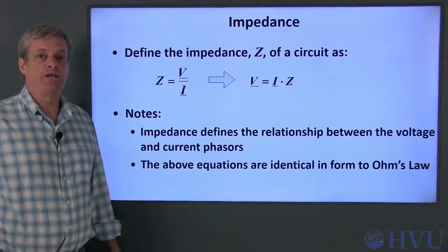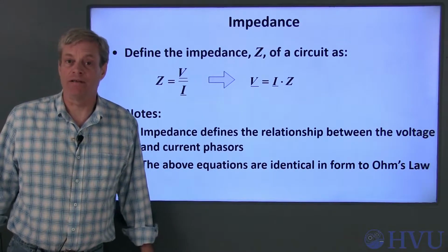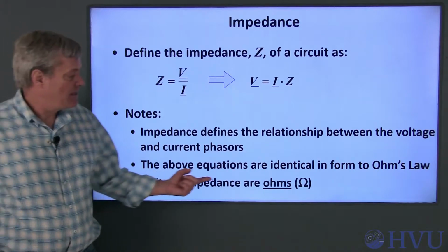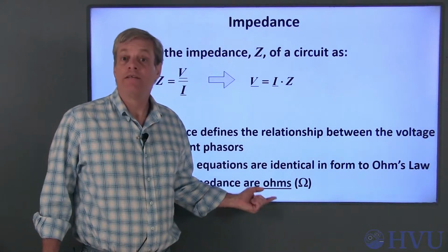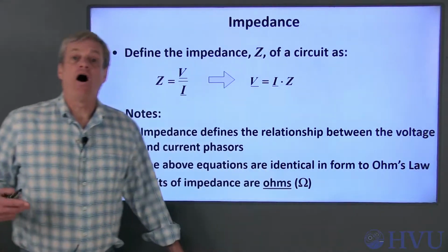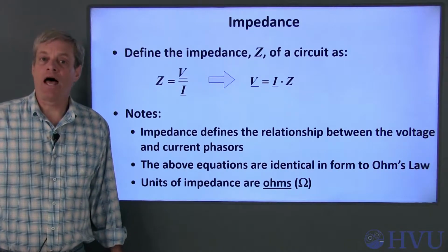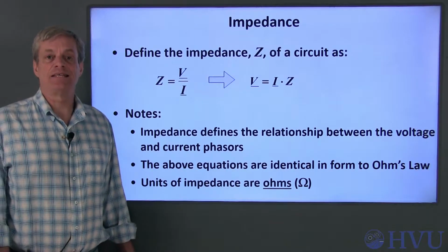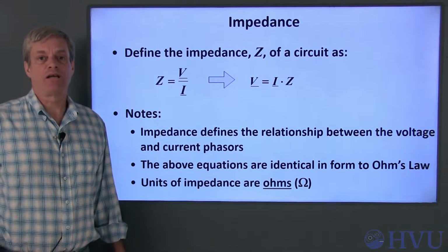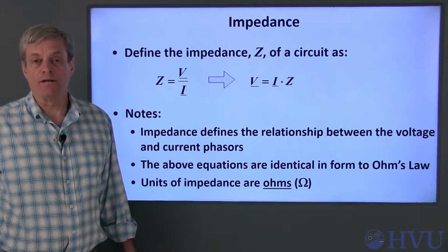Impedance is defined as the ratio of voltage to current phasors for any passive circuit element. Because of impedance's similarity to resistance, the units of impedance are selected to be ohms. The symbol is the same as for resistors, an uppercase omega. Always keep the appropriate assumptions in mind. Using impedance implies that you're performing a steady-state sinusoidal analysis. Don't try to use impedances if the response you're calculating includes the natural response or if the input isn't sinusoidal.